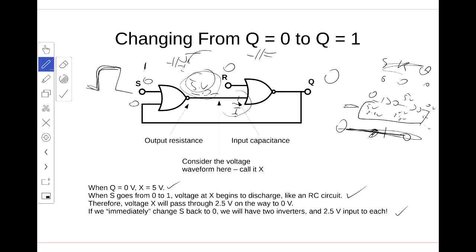If I had to summarise it quickly, I would say there is a capacitor between these two inverters. When I change state, I have to either charge up this capacitor for logic 1 or discharge this capacitor for logic 0. But if I were to partially charge that capacitor, I can get it stuck. Well, I can bring it to any voltage I like. If I apply a very short pulse on the set pin, I can bring this capacitor to any voltage I want. When I remove the pulse on the set pin, I go back to two inverters.